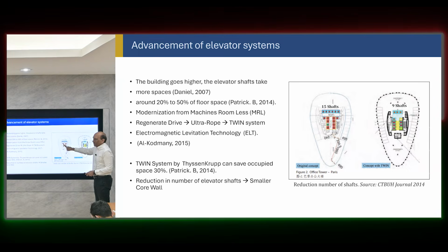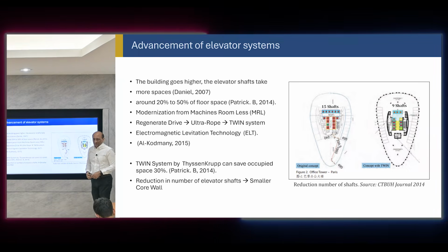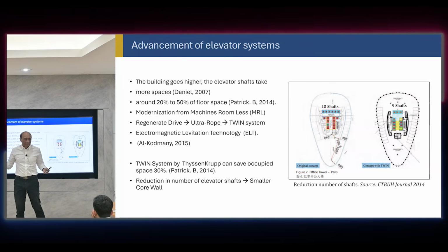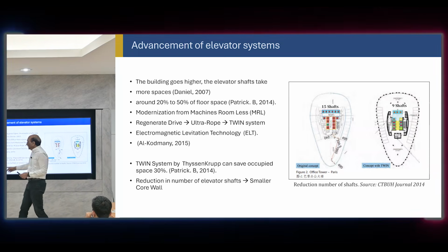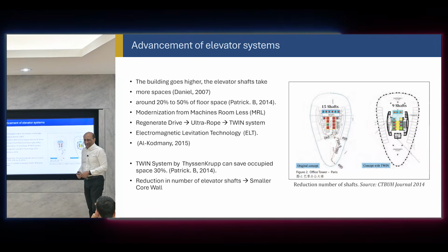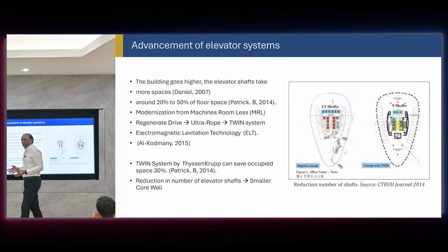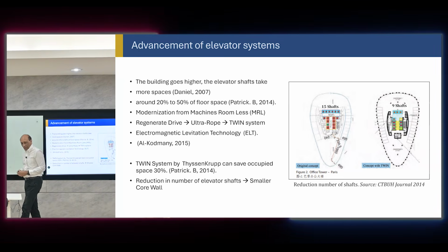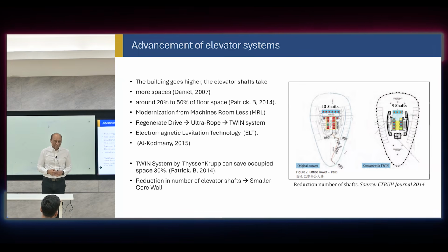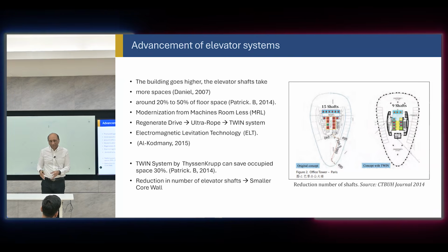Previously, the old design of the elevator required 15 shafts, so the core would be very large, which is very good for structural engineers because you can use the entire core. The new technology only requires 9 shafts. So from 15 to 9, because the elevator technology improved, the number of shafts has decreased with better performance, which means that structural engineers now get a smaller core to deal with for the same height.